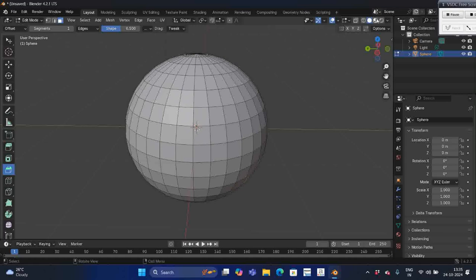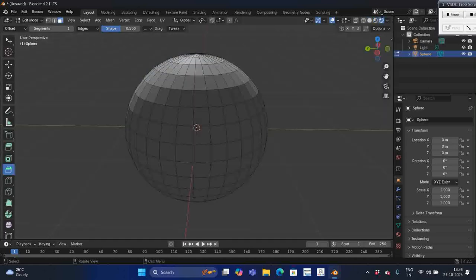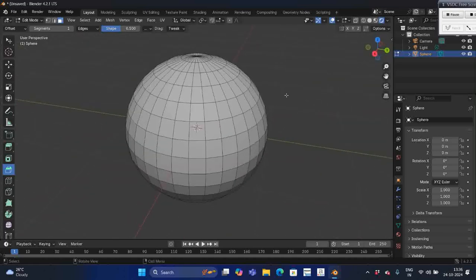The other tools are also there, like material mode, where you can color your object. You can go to this part and select any color to apply on your object. These things allow you to change the colors and everything. That will be done after rendering and other things, which we're going to see in the coming videos. So the three important things in edit mode are knowing about the vertex, edge, and faces, because only these things are going to modify your object completely.